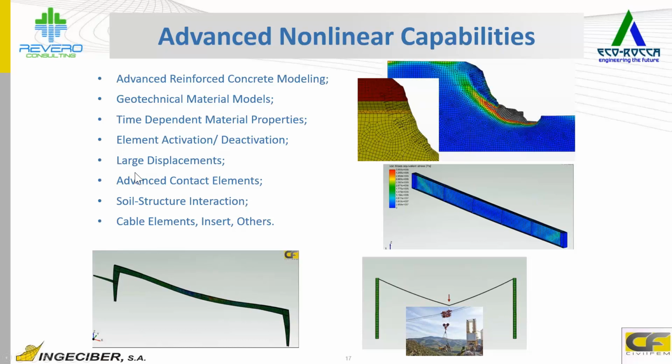There is the possibility to run the software in large displacement mode, and have also advanced contact elements between finite elements. Soil-structure interaction is modeled, and we have also the capability of using cable elements, inserts, and other things, for example, to model soil nails, rock bolts, and cables.